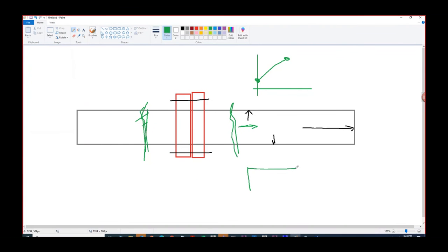Like in the previous example, we have seen that you have a total load. This total load can be visualized something like this. This is your force, 0, and your force is something vibrating like this. Then what you can think about is this is the mean load. About the mean, this much is the static load. About this static load, this much is the fluctuating load. Those concepts can be used for any fatigue analysis purpose.